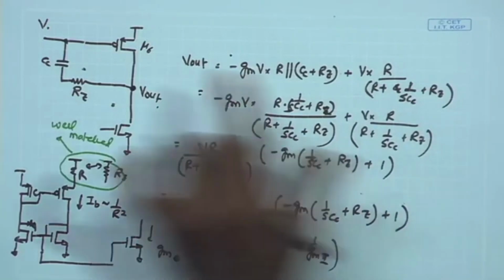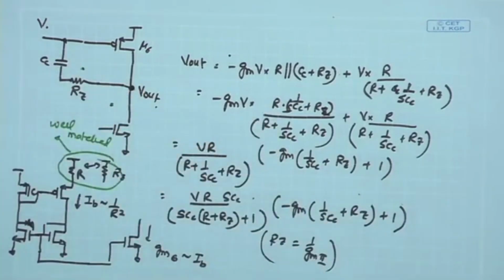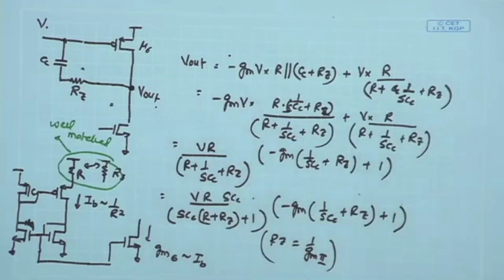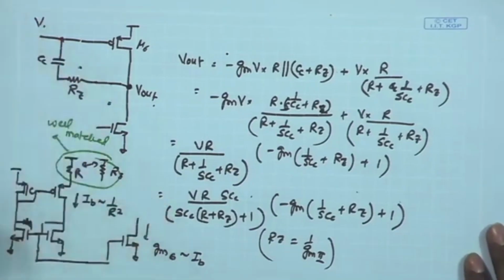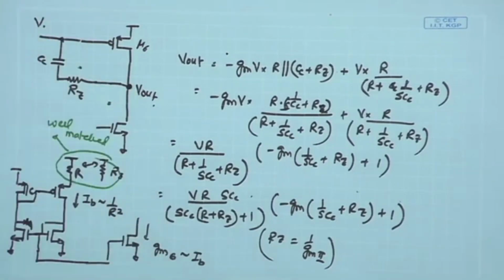And moreover, it is providing something similar to a shunt feedback, just like we have for the main amplifier. There also we have discussed that if the feedback resistor RZ or RF that we had in the op amp is having a shunt configuration, the current noise injected by that at the previous stage is relatively small. As a result, it is not going to have significant impact. And once again, we will revisit that noise analysis while we discuss the transistor level noise analysis, and there also we will try to once again justify with a little bit more detailed analysis that the RZ appearing in the shunt feedback does not significantly corrupt the input signal or does not significantly add to the noise of the amplifier.